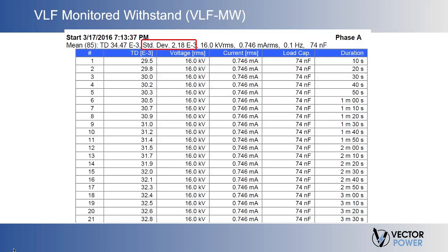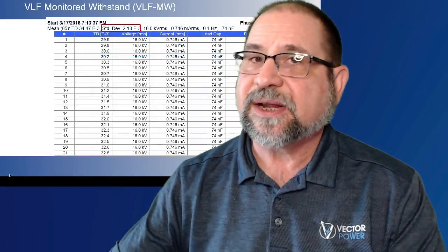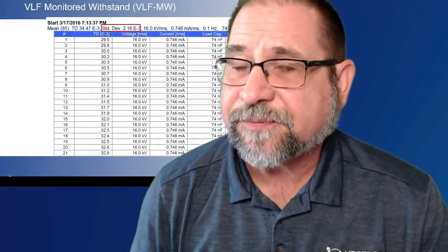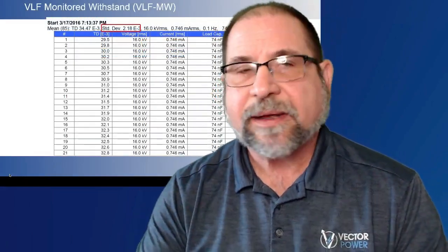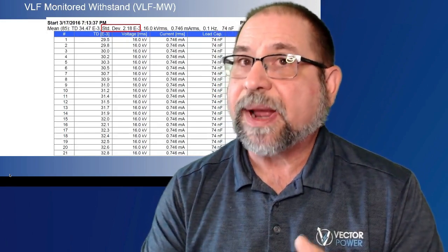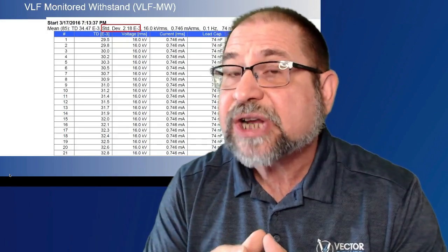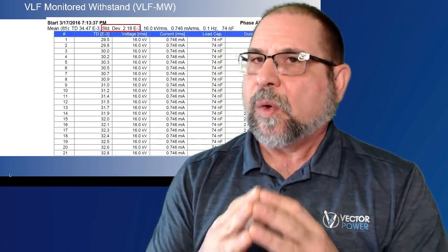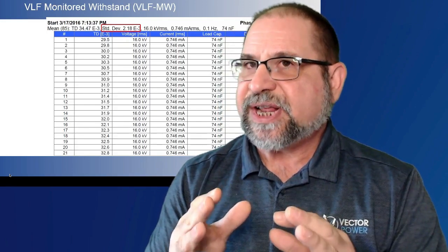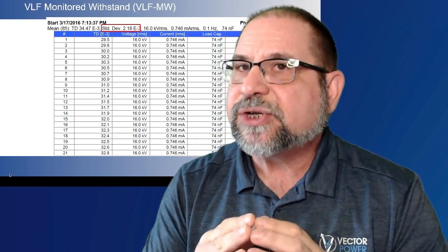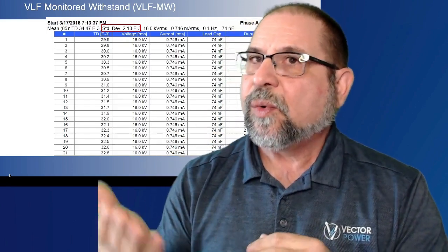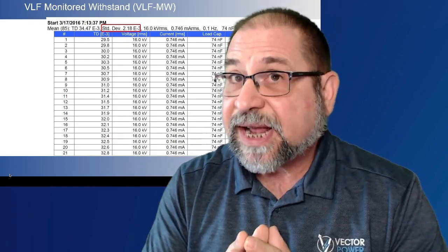And this is really good information for when we are performing tests on electrical power cables. By monitoring the tan delta values or by monitoring partial discharge activity, if we do begin to see the deviation level begin to grow, we can immediately stop the test.